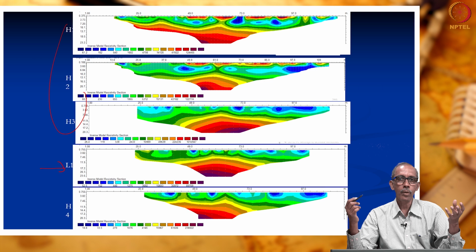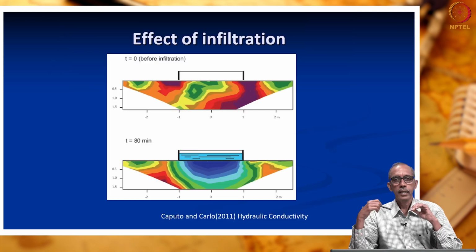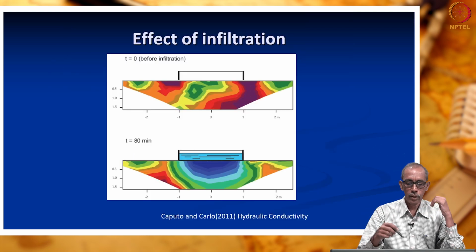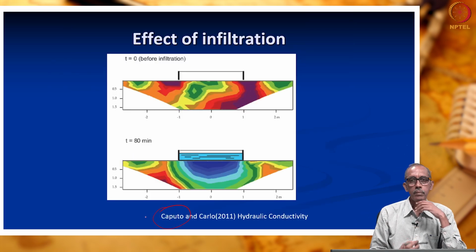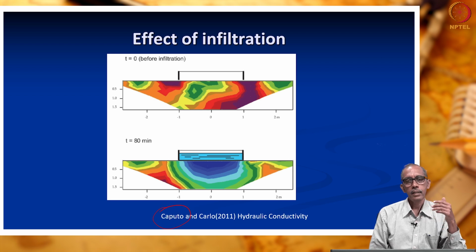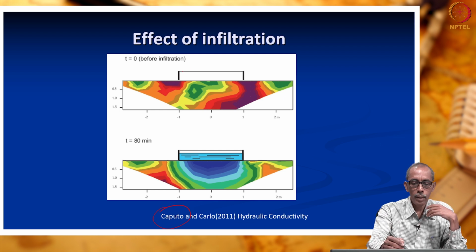So, this is a time domain resistivity survey. That means the 4th dimension of time has also been taken into account. Here is a study carried out by one of my collaborators from the Water Research Institute, Bari, wherein they are making use of electrical resistivity survey to understand the effect of recharge from a small percolation pond.